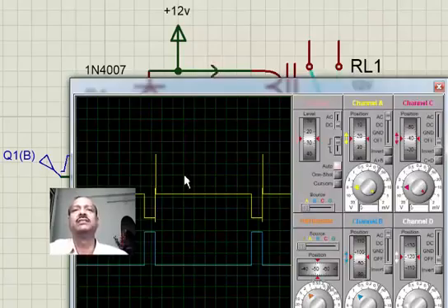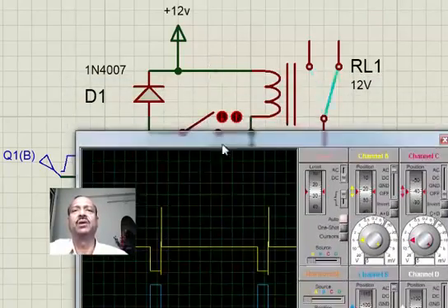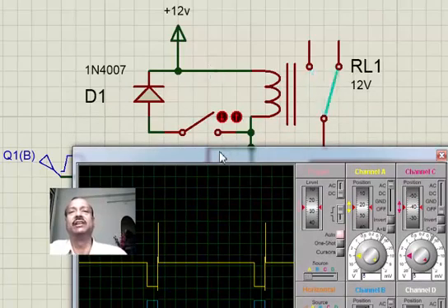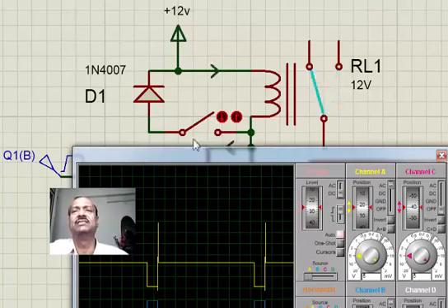So this is the function of that diode, and people call it a freewheel diode, people call it a snubber circuit, people call it dV by dt. So many terms they use, of course, as far as the engineering concept is concerned. But in layman's language, it's as simple as this. The energy stored in this is dissipated during the off time through this diode. During the on time, this doesn't have any function. This is the real function of this particular diode.